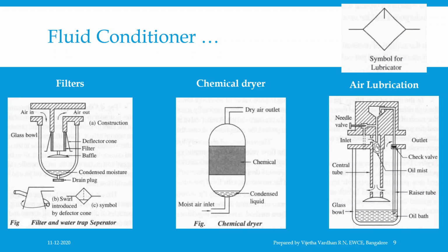This pressure difference at the inlet and after the Venturi effect causes the oil to rise in the riser tube. This oil comes out at the inlet point of air in the form of fine spray and mixes with the air. A needle valve adjusts the pressure difference across the oil jet and hence controls the oil flow rate.